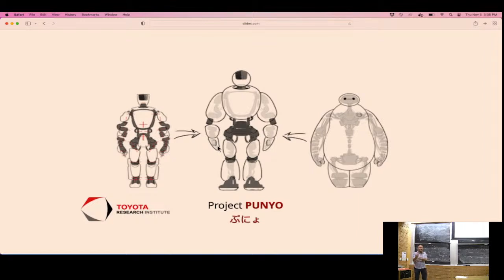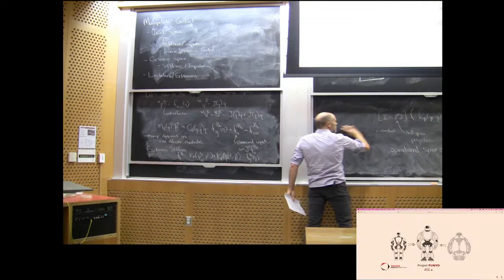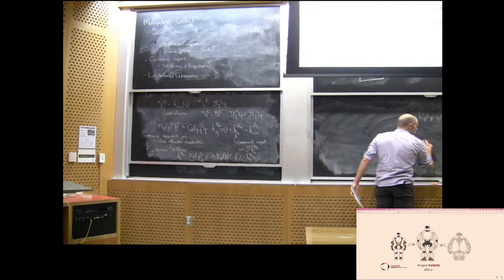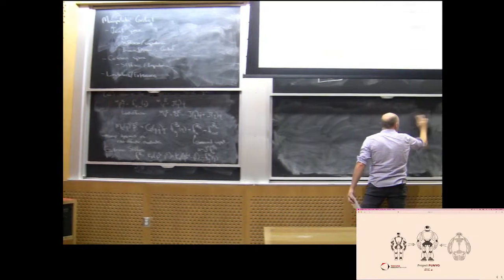I think we understand that the joint torques are not going to get it done unless you had a lot of links. Okay, so I'd say that's the biggest limitation of this: the impedance control, stiffness control, end effector view of the world needs you to know where the end effector is.